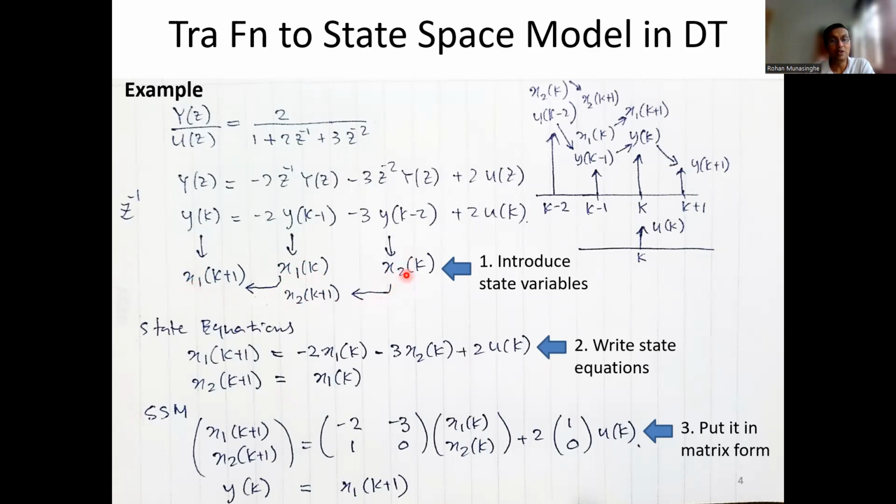but we don't assign any 0k here, right? We do the assignment starting from the oldest one and work it out to the left hand side, but when it comes across the equal sign, we don't continue any further. So now we have two state variables, x2 and x1 at time k, and also x2 and x1 at time k plus 1.